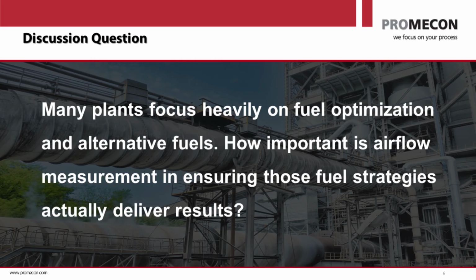Thank you. Yes, well, these are discussions during those conferences, but also during plant visits that I do on a regular basis. And I speak mostly these days to North America and the US, but many plants don't really have a reliable kiln inlet gas analyzer, nor do they have any frequent free-lime measurement. And these would be the two absolutely critical data to optimize and control the pyroprocessing.